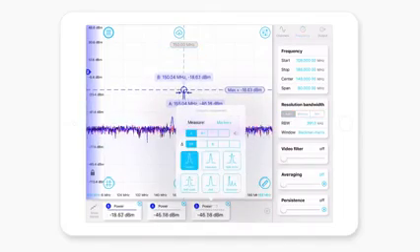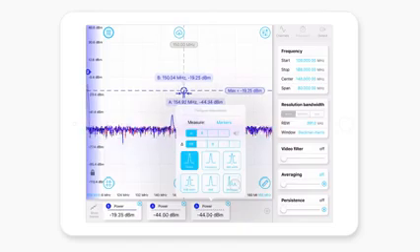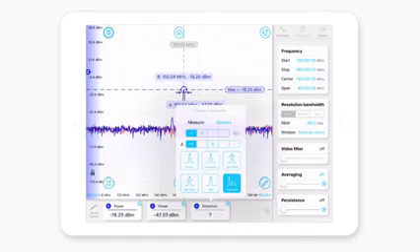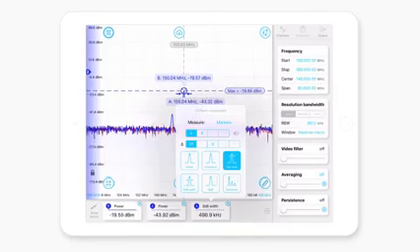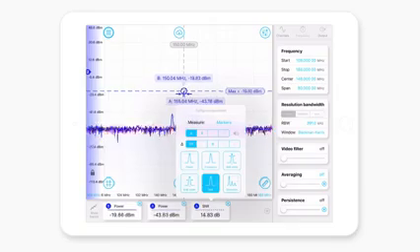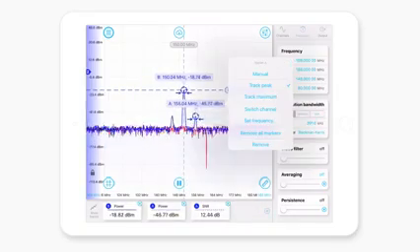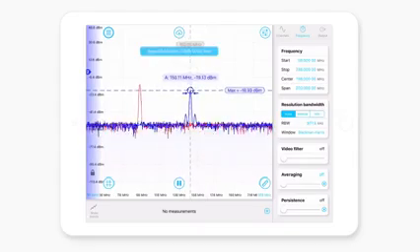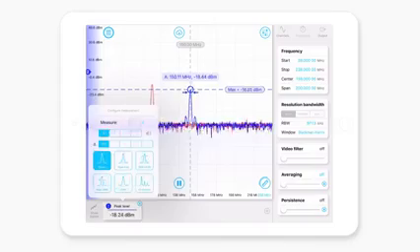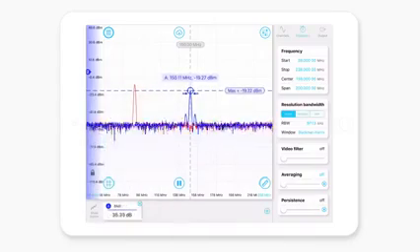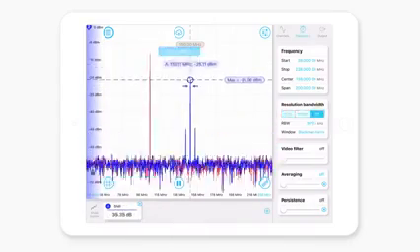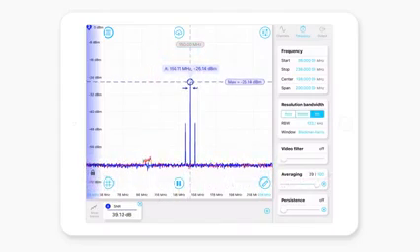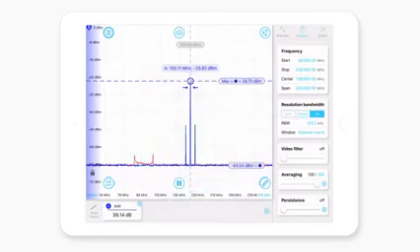So, if you wanted to measure things like total harmonic distortion, then you could do that. 3 dB width, which is handy. Signal to noise ratio is another handy measurement to have around. So what we might do is remove all markers, drag one up here, and then on marker A, I want to measure signal to noise, then it's going to give me the best estimate as to what that is. And I'll quickly have a look here and see what the measurement is, and it's pretty close.